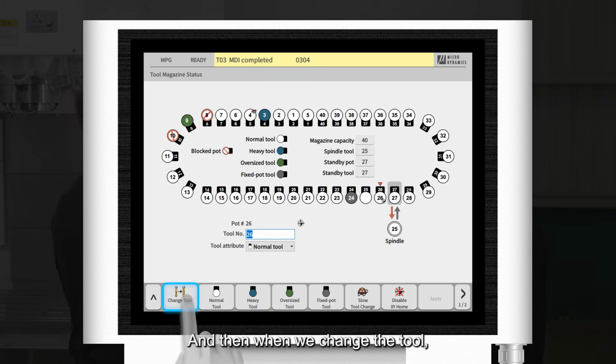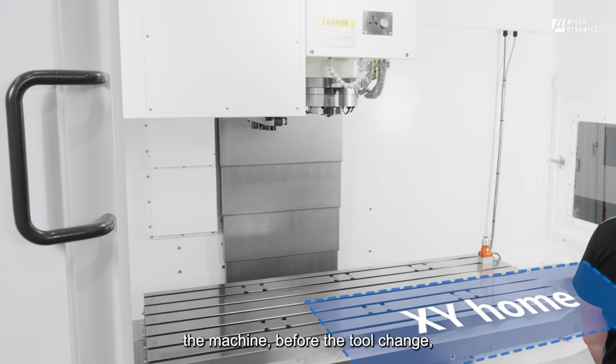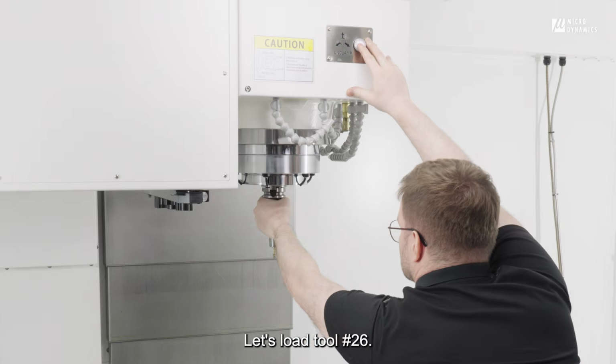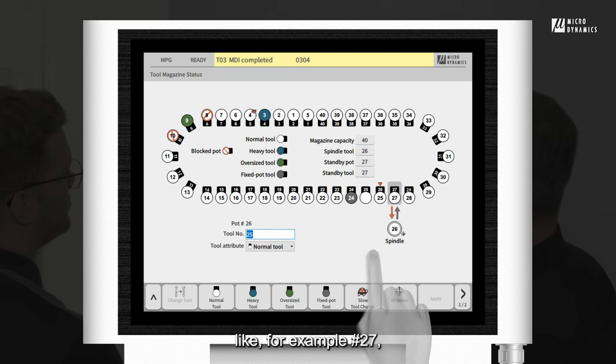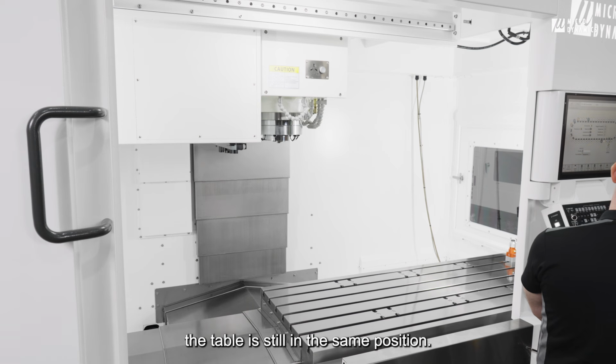And then when we change the tool, the machine before the tool change is going to move the table to the XY home position. Let's load tool 26. Then when we do another tool change, for example 27, the table is still in the same position.